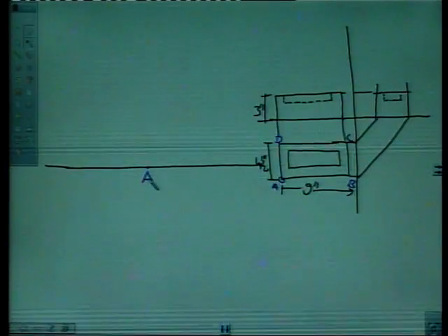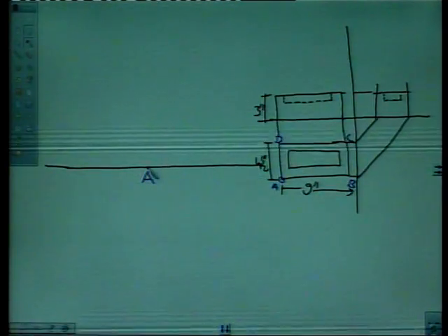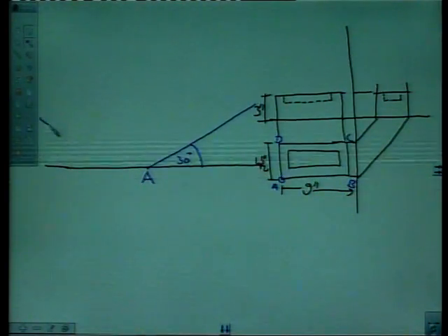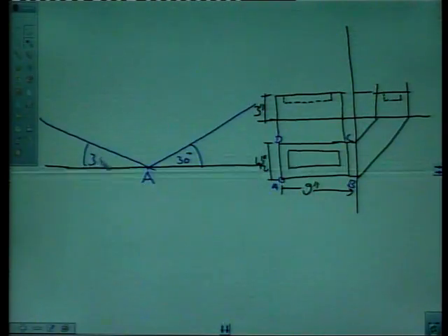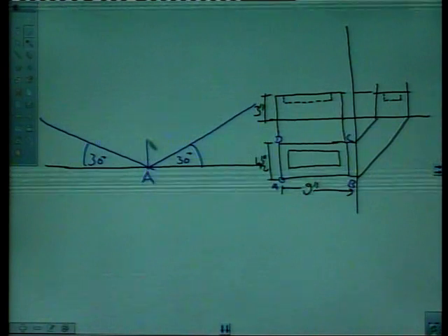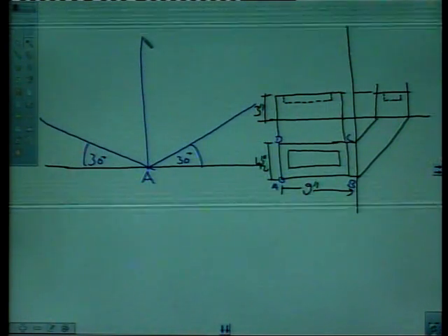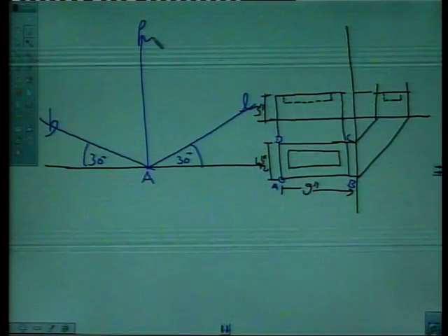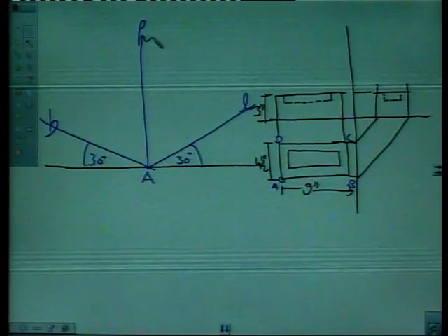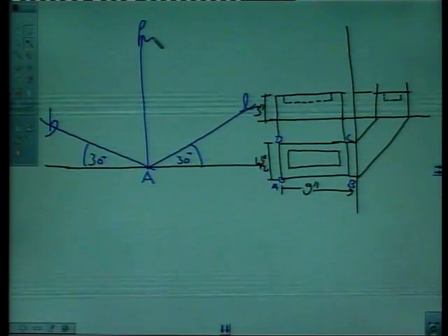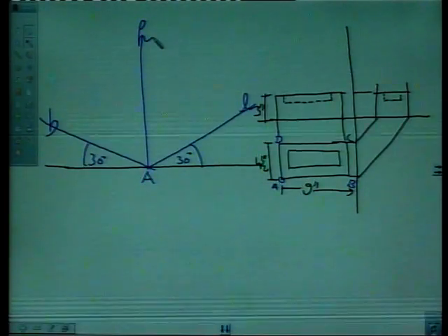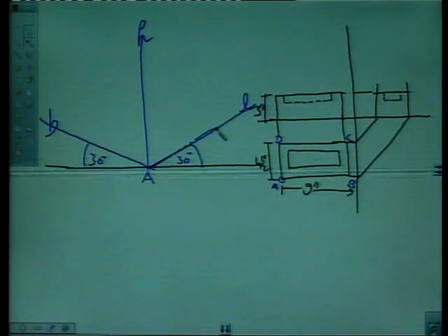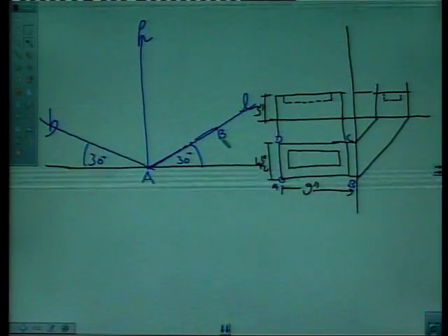Start by drawing 30-degree angles, both sides, like one angle here, 30 degrees. Second angle towards left hand side, this is also 30 degrees. And one vertical line, right? This will represent, say, length, this will represent breadth, and this will represent height of the object, right? So, first say we want to represent length of the brick. Length is, say, 9 inches. From A, mark 9 inch, say here. So, this point will become B, right?